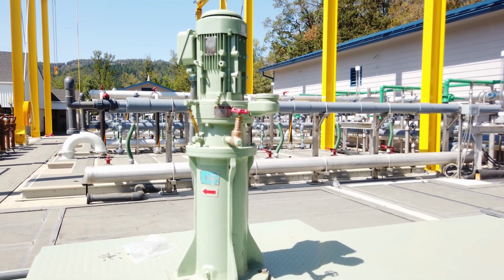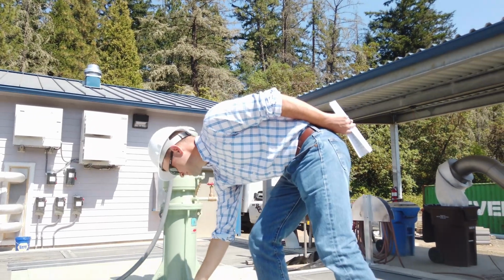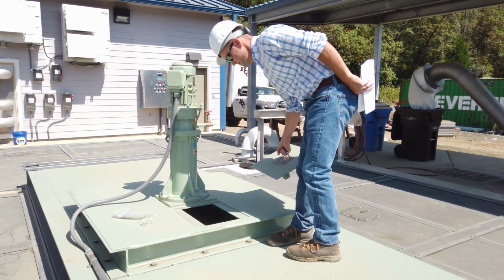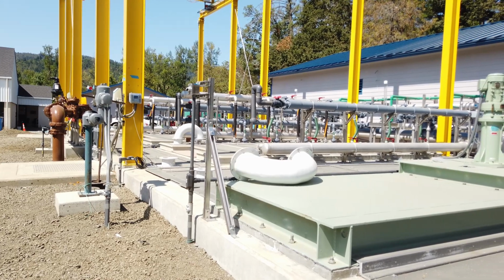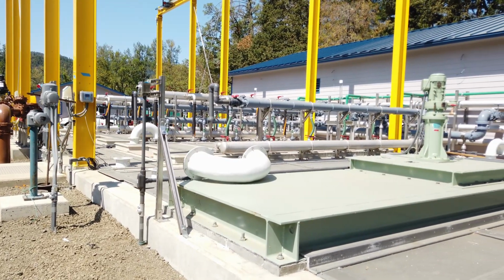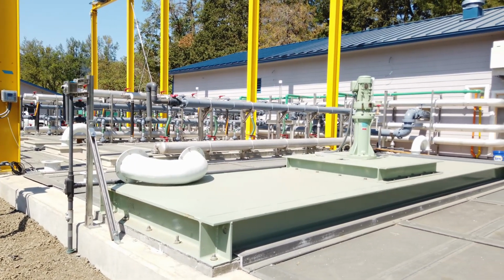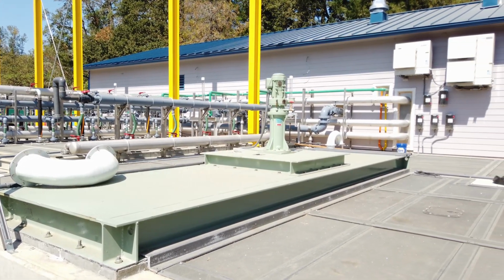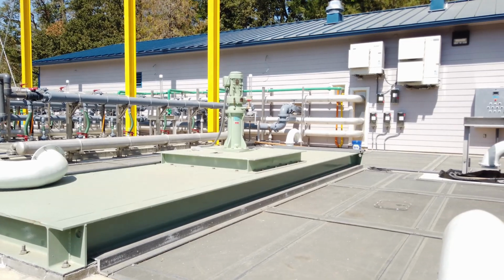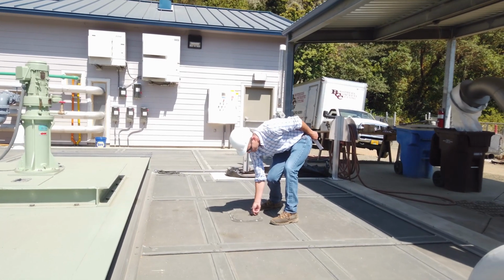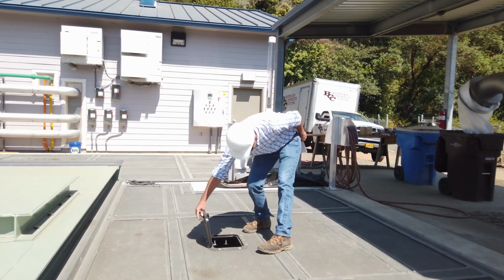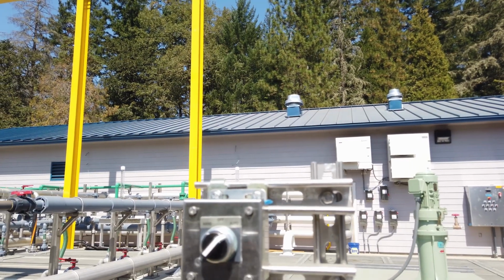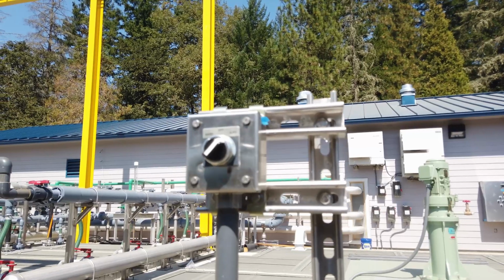The propeller forces the liquid in the tank to descend and creates a good circular motion and mixing in the tank liquid column. This is a low energy process with only a 2 horsepower drive motor. The motor is easily accessible for maintenance and inspection. The tank and all the process tanks in this MBR system are approximately 18.5 feet deep. The DO is currently less than 0.2 milligrams per liter and often close to zero.